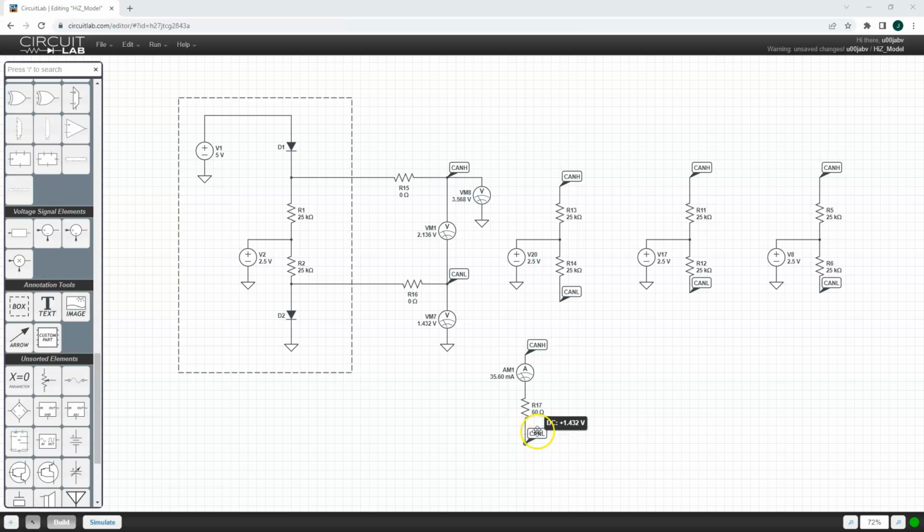I did put an ammeter in here because I need to show it. We're going to take the two terminating resistors, put them in parallel, and model them as 60 ohms. I have all of the other devices that are on the CAN bus. They are in the recessive state or the listening state. And so what I've shown here to simplify is I have the fuel pump trying to transmit one dominant bit.